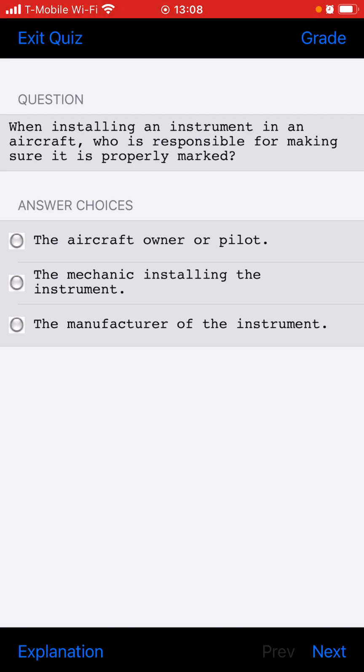Why are fusible plugs installed on some aircraft wheels? To release the pressure generated by heat buildup before a tire blows. How can a pilot determine that the landing gear is down and locked? A green light or lights are another type of visual indicator.